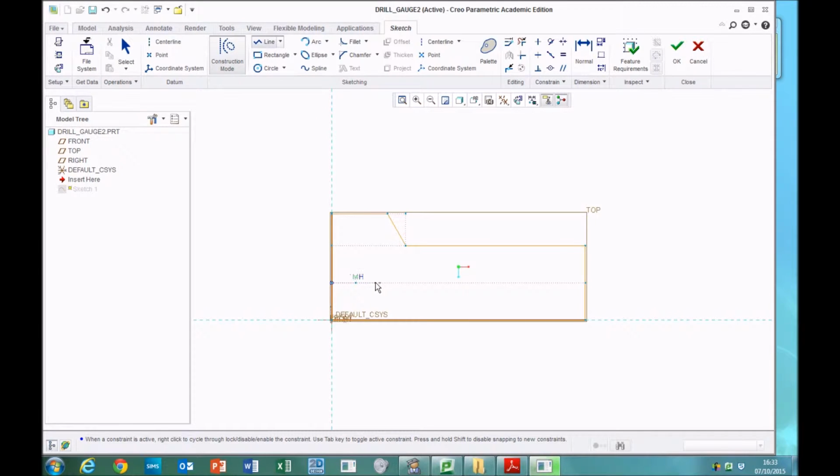Now as you're drawing, try and avoid any of these M's and L's, because it will assume that you want it to be the same length or the same distance as another line that you've previously drawn, and we don't want to do that. We want to tell it how long it's going to be. So just try and avoid the M's and the L's. Mouse wheel to stop. Draw another one. Click. Click. Mouse wheel to stop.